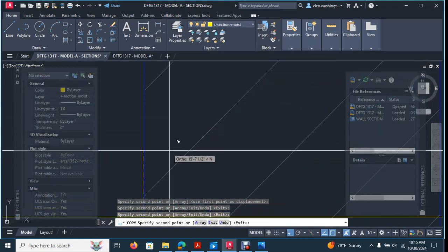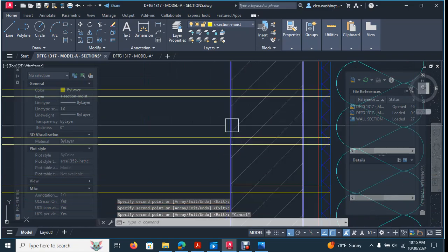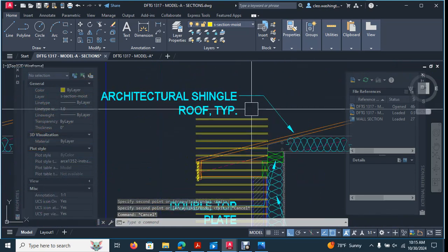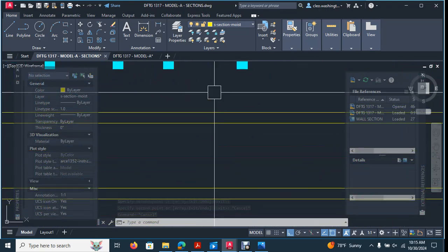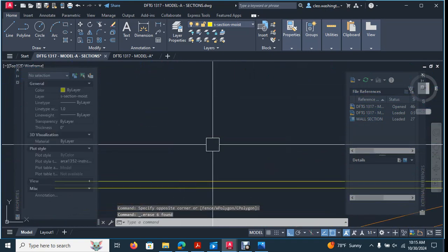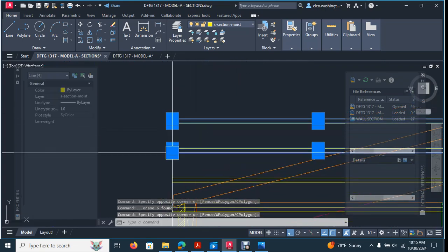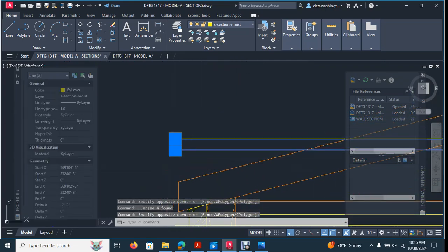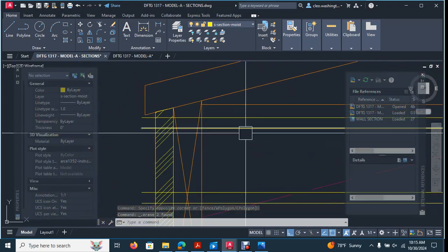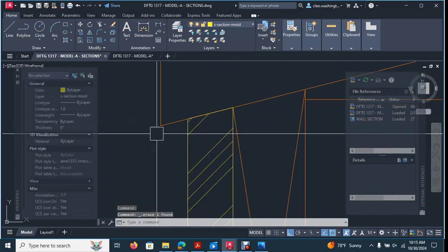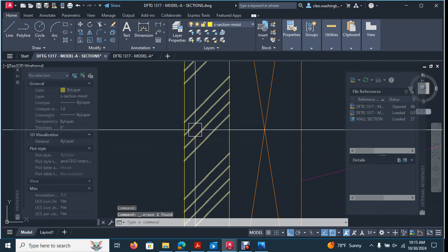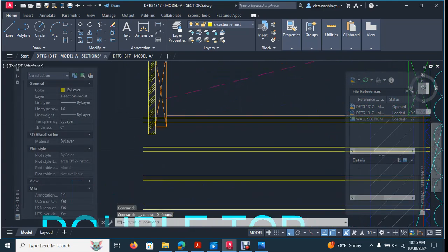And let's do one more right here, okay? So as you can see, it goes all the way up. But we're going to delete some of these. Let's go ahead and take these out because we don't need it. I just want to show you this is what coursing means. So whenever you see that term, hear that term coursing dimensions, you need to make sure your bricks are in course. So let's go ahead and take these out. Coursing meaning the size of the brick taken into account with the 3/8 inch mortar joint size, right?